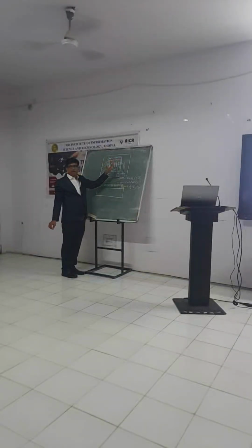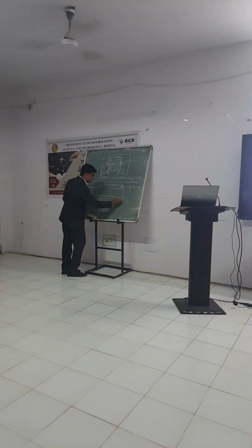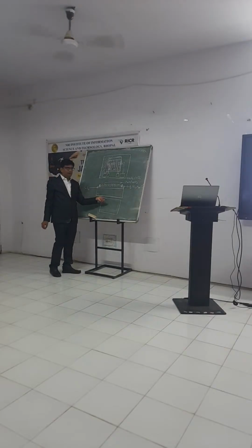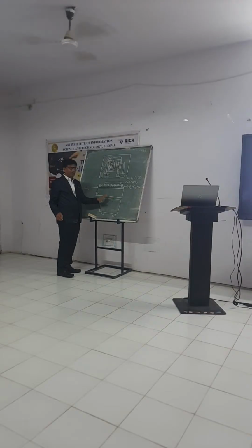The rest is coated with an oxide layer, and for the electrode, where do you have to deposit it? Over this oxide layer only. Clear? See what your electrode structure is. Let's suppose this oxide layer is deposited over my heater. So let's suppose this is your heater here. This is your heater contact, and the remaining area has oxide.